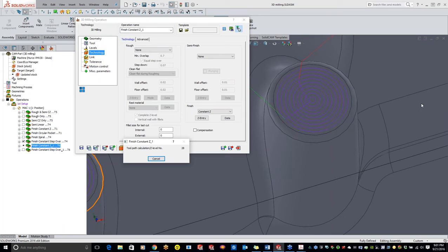James, when I'm 3D milling a large mold and I get to an area where the vertical wall only has about a 1 degree draft, it sometimes won't do a finish on the whole area. Like I said before, James, I think what we need to do is get into a GoToMeeting on your particular part. There are a lot of options in the 3D milling to accommodate those more vertical walls.